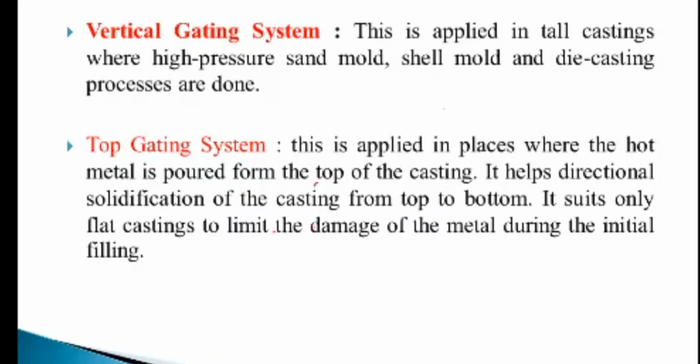What is directional solidification? We must design our gating system in such a way that the farthest portion of the metal from the point where we are feeding should solidify first, and solidification should start from that point.